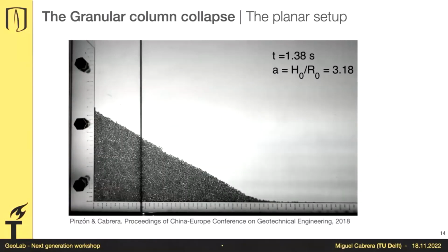In a fluid, the same boundary conditions appear, but you have the additional effect of the water slowing them down. Because of that loss of kinetic energy, they don't manage to reach that far. So in an immersed experiment, the slope you reach is not the repose angle, but is due to that interaction with the fluid.